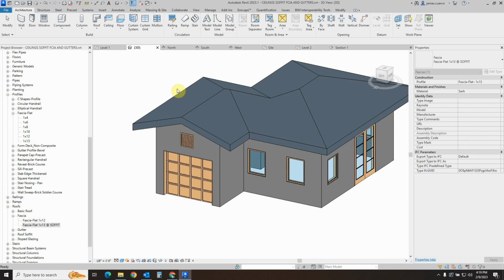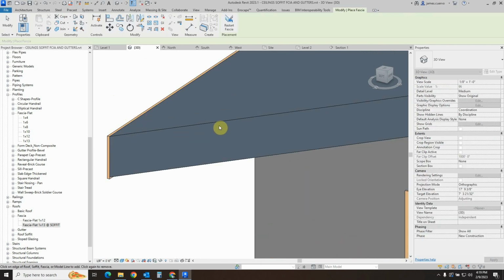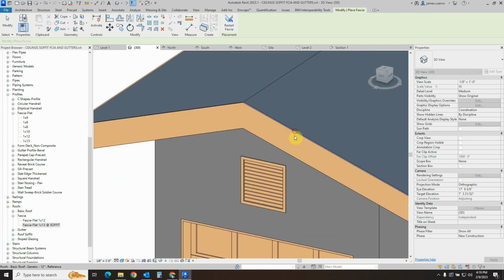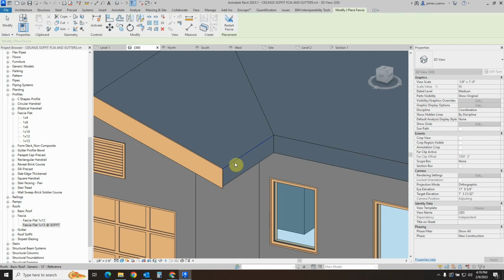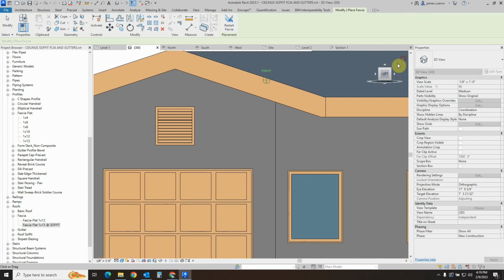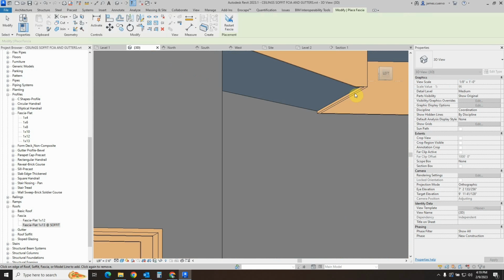We're not going to do the whole thing. Okay, so we go to the roofs, fascia, and we select the upper level edge of the fascia here, of the edge of roof. In this one also, here, so we can basically see what it's going to look like more or less in this way. And so right now we've added our fascia, and as you can tell, we have a little bit of a lip here to receive our soffits.